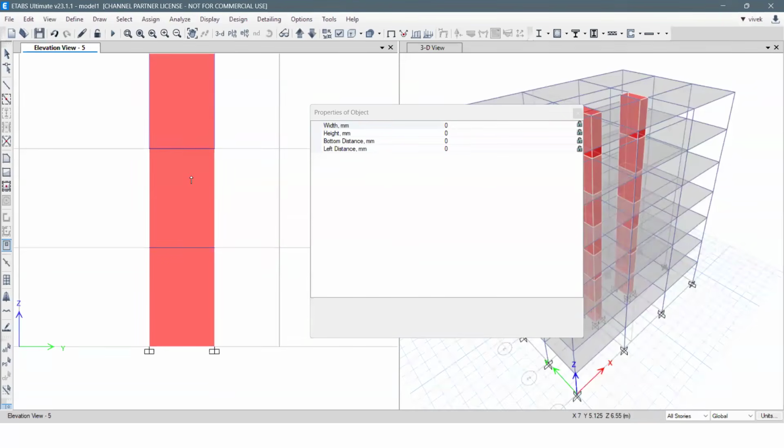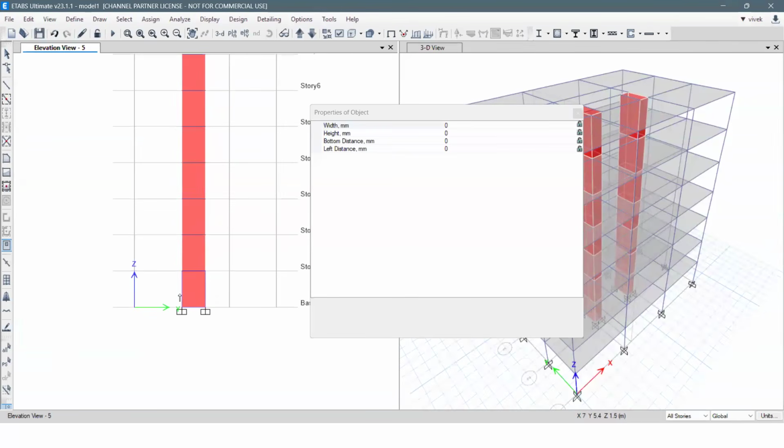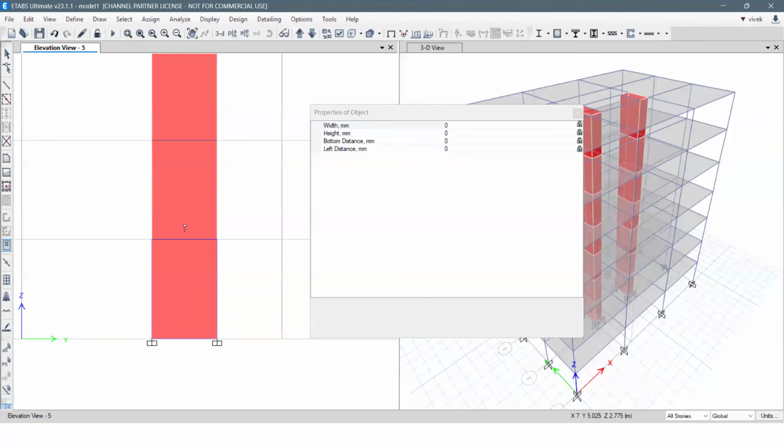It will snap to the wall panel in each story as you move the mouse on them. There you can quickly click and then start with the help of the small dimensions and draw this opening. Click, and then the opening size also gives you this, and you can create the opening like this, right?